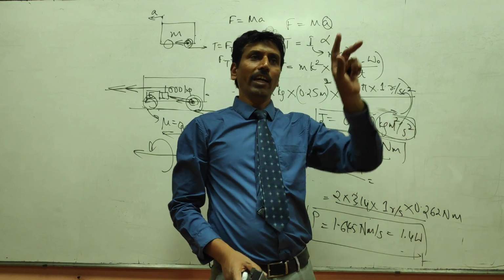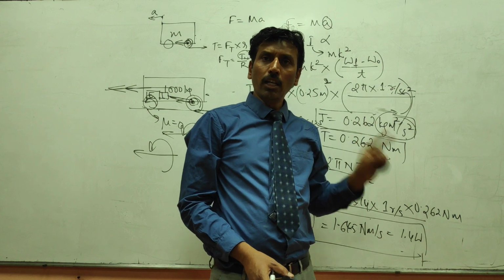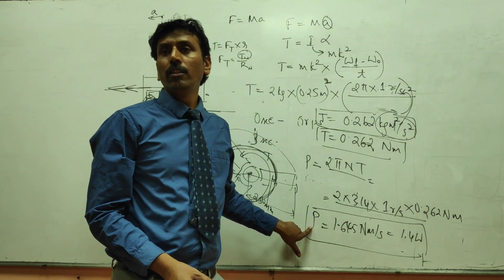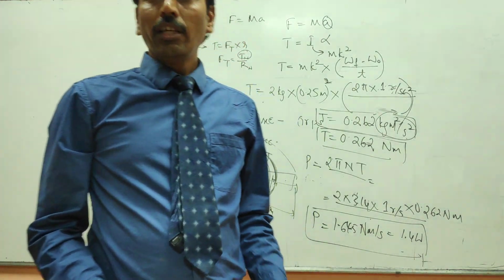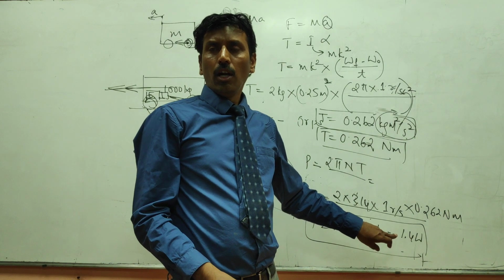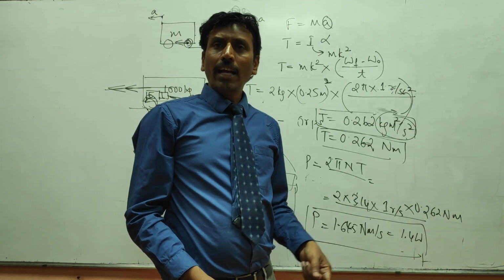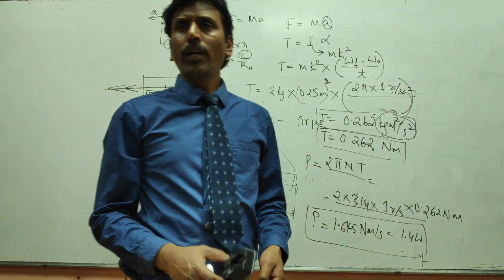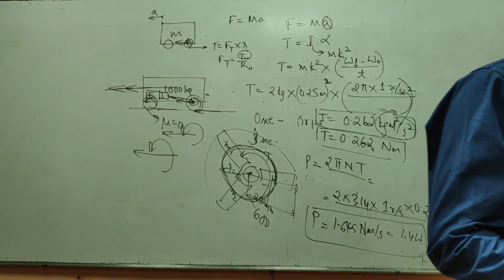If you can make it proper with the weights and the radius of gyration, everything proper, you could definitely guess the power of the fan. We are not running it at full speed now, sir. Yeah, maybe for that reason the watts consumed is very less. And also we might have made some error in calculating the angular acceleration. In this way, you can definitely guess the power consumed by a fan.